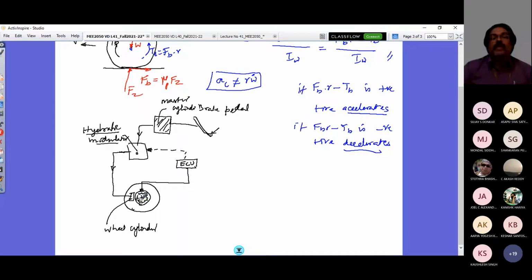Once locking is prevented, again the signal will come here and it will sense that the speed is going beyond some value. The braking action should not happen all of a sudden with locking; it has to happen gradually. So within a few milliseconds it has to function: release pressure, increase pressure, release pressure, increase pressure, like that. The pressure reduction is not to zero, and again it has to increase, then decrease. So it has to reduce, hold, increase, hold, reduce, hold, in a cycle. There will be threshold values, looking at R times omega, the corresponding speed, or R times omega dot, which should have some range of values, and accordingly this would be acting. This is how your ABS functions.